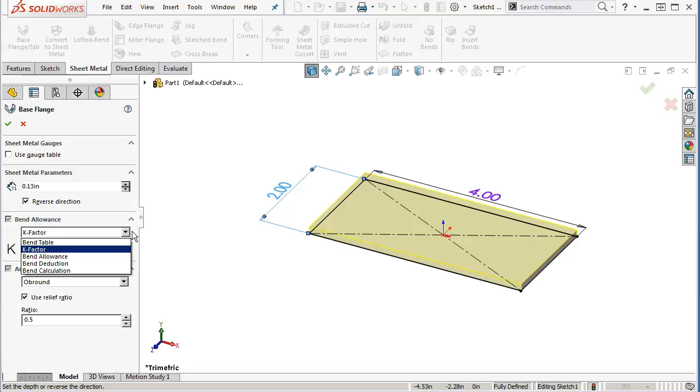All right, so on my side, I don't do enough sheet metal to get to this level of detail. If you do a search for these tables, they're certainly going to be more accurate than what we're doing with the K factor. The other thing is, if I'm sending this out to a sheet metal shop, then what I'm interested in is, hey, if I send you this geometry and I have a K factor of about 0.3, you can send me the quote, send me the estimate based on material sizes and bends and everything else. And then when you get it, you build in your bend table, you build in your bend allowances, and can make it. I'm good with that. I don't need that nth degree on my design side.